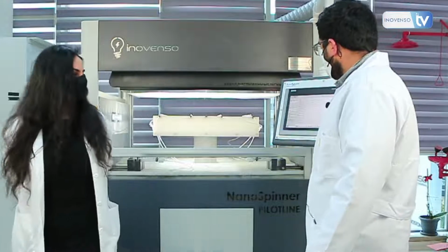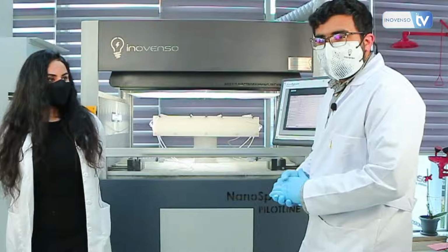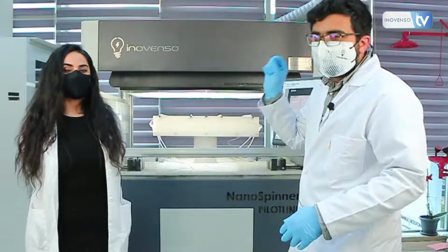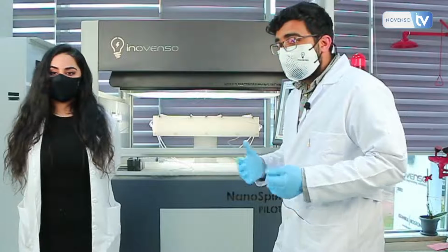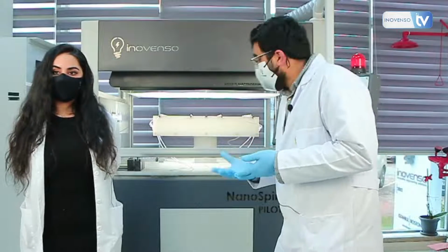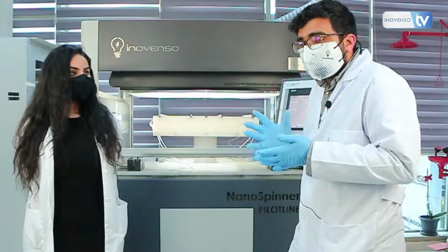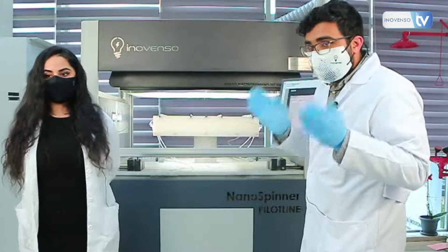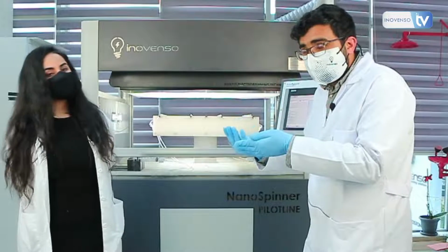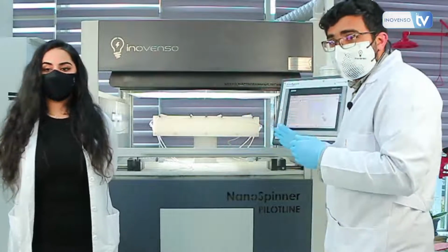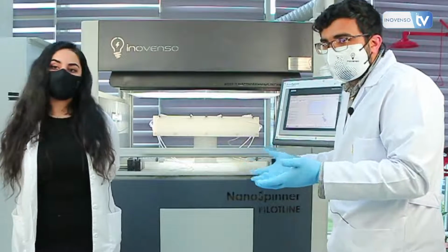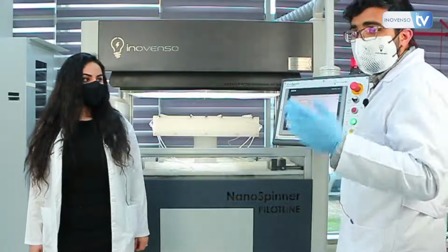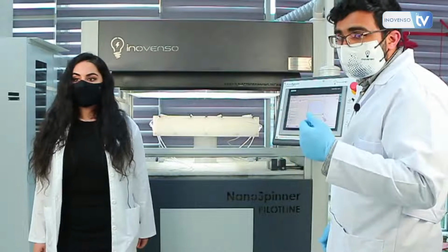One other key function I want to tell you about is that suppose you have a recipe ready. I understand it gets complicated and difficult when you're mass producing something and you have to keep putting in the same parameters day after day. Luckily, in our machine we have a data registry, so to speak, where you can save or store your recipe data in the control panel. You can enter whatever voltage, flow rate for that particular solution, and thickness. All of that can be ready-made for you once you've optimized the parameters and you're used to the polymer. Once you have a ready recipe, you can store it as a function in this machine, and it's one click away from starting production and continuing.